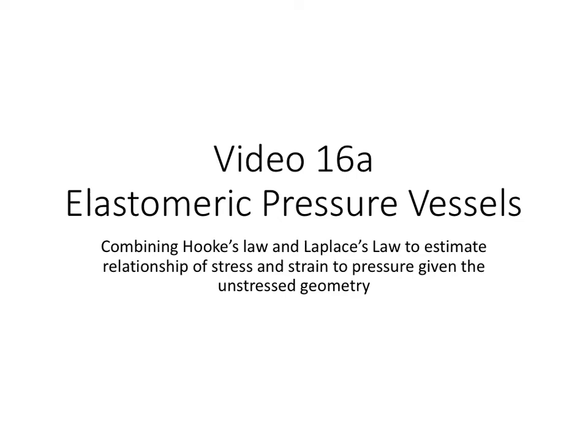In this video, we talk about elastomeric pressure vessels, which are pressure vessels that expand enough that we cannot use the original radius and thickness to estimate what stress will occur when we expose them to a given pressure. To do this, we'll combine Hooke's law with Laplace's law in order to predict what happens under stress.